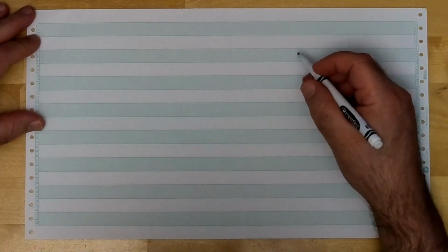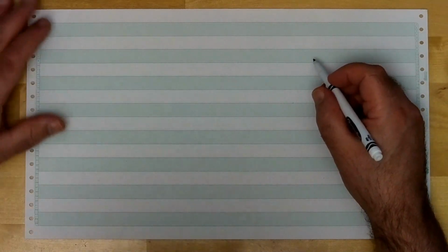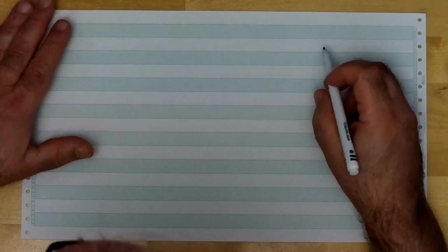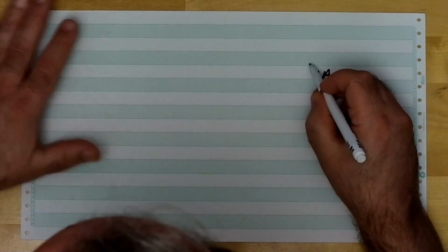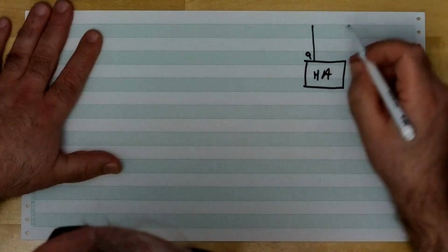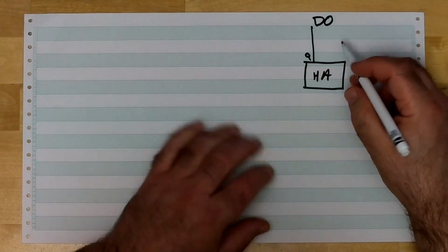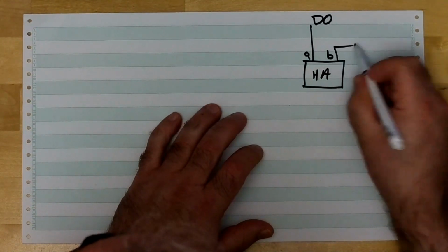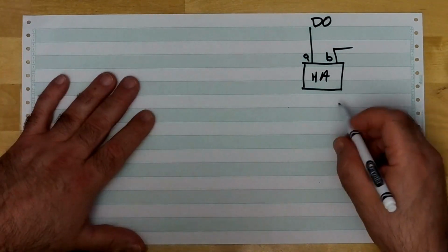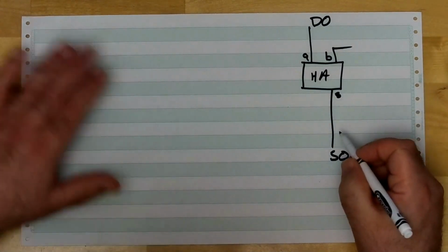So we know how to add two 1-bit numbers with a half adder. Let's see how we can add 1 to a multi-bit binary number with a half adder, or in this case, multiple half adders. That's why we abstracted it away. So what if we do this? Let's take a half adder and hook it up like this. Take the A input, and we'll call that D0 for now. We'll see why in a minute. The B input, let's leave that sitting there for a minute. The sum here, let's call S0, is the sum output.